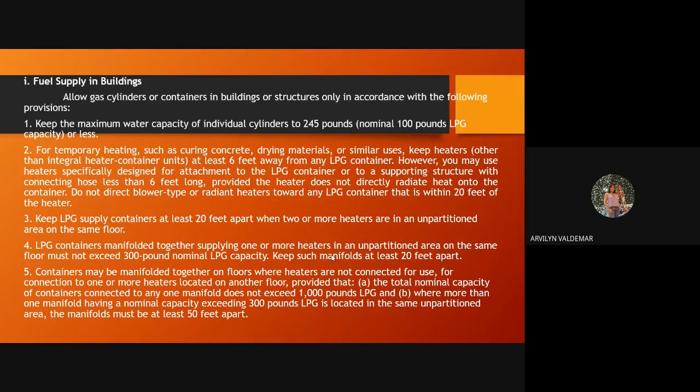Where was I? However, you may use heaters specifically designed for attachment to the LPG container or to a supporting structure with connecting hose less than 6 feet long, provided the heater does not directly radiate heat onto the container. Do not direct blower-type or radiant heaters toward any LPG container that is within 20 feet of the heater. Next, keep LPG supply containers at least 20 feet apart when two or more heaters are in an unpartitioned area on the same floor.